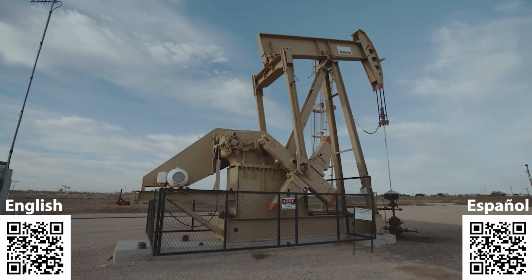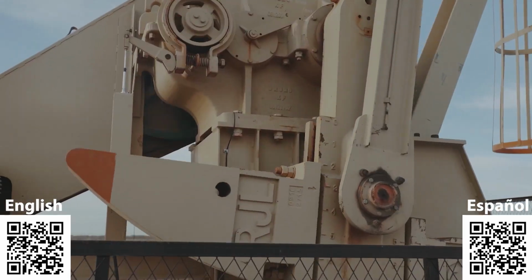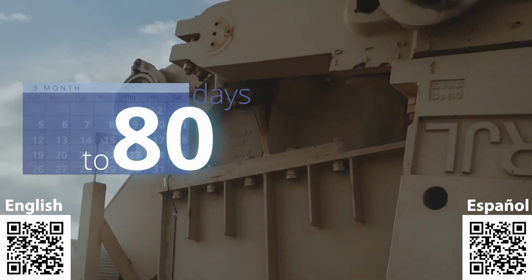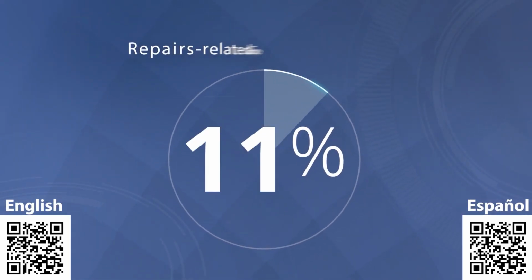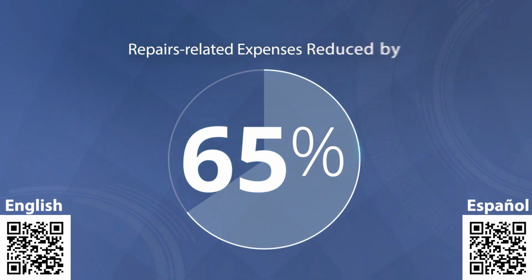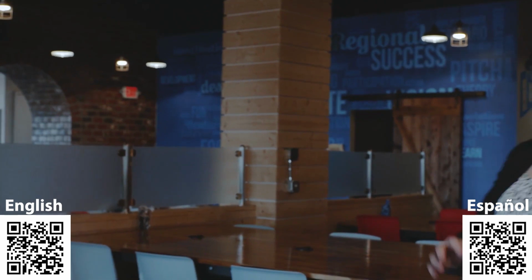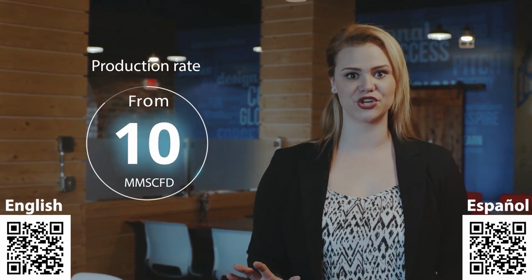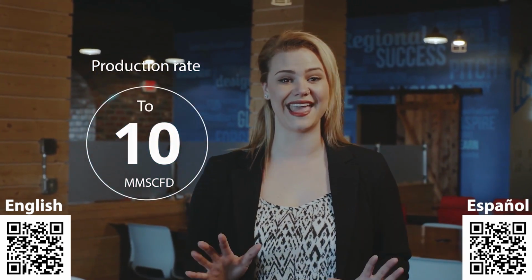By utilizing Masterflow's external sleeve and cage design, they were able to extend this period to 80 days. At the same time, repairs-related expenses reduced by 65% using the external sleeve. And most importantly, the company was able to increase their production rate from 7 million standard cubic feet per day to 10, due to the improved erosion resistance by Masterflow's external sleeve and cage choke valve.